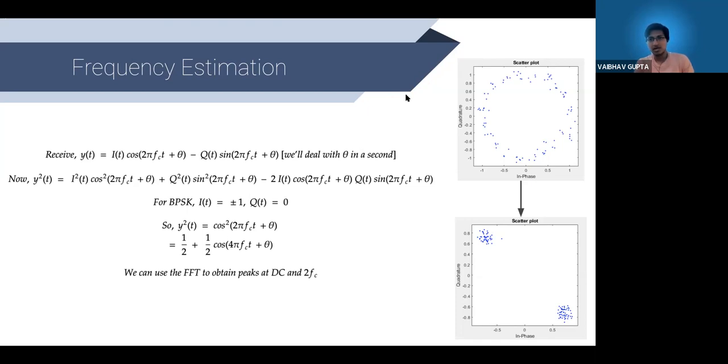The problem is kind of what Tyler was hinting at. The microcontrollers have different oscillators that define what 100 hertz means. While 100 hertz might mean 100 hertz for one, on the other the oscillator might drift by 0.1%, and now 100 hertz is actually 101.